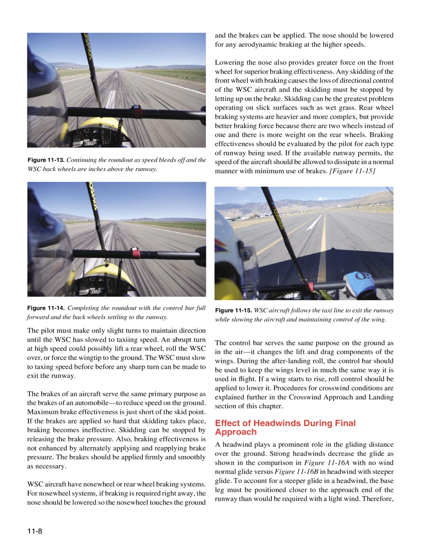on the ground. Maximum brake effectiveness is just short of the skid point. If the brakes are applied so hard that skidding takes place, braking becomes ineffective. Skidding can be stopped by releasing the brake pressure. Also, braking effectiveness is not enhanced by alternately applying and reapplying brake pressure. The brakes should be applied firmly and smoothly as necessary. WSC aircraft have nose wheel or rear wheel braking systems.